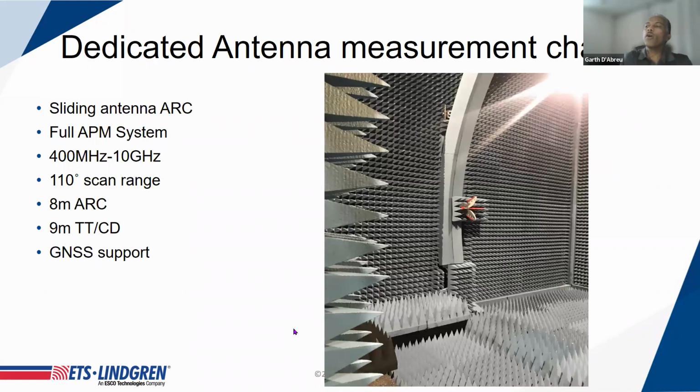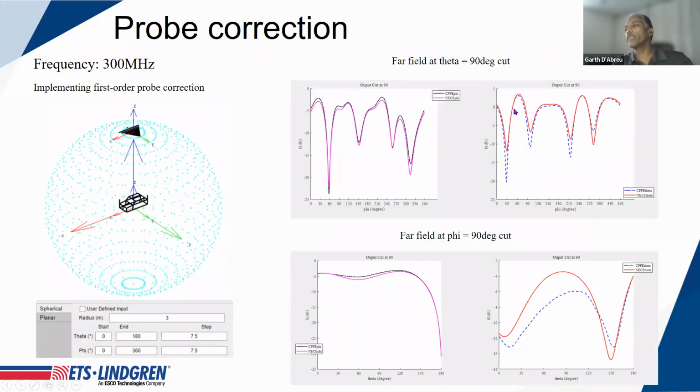This is one example of an upper hemispherical type scanning measurement setup, where the vehicle under test would be positioned and the antenna would scan over from the horizon over the top of the vehicle. This is a little model illustration of a vehicle under test sitting in a scanned bubble, as if it's floating in space. It allows you to make a completely spherical measurement of the vehicle. And from that, you can calculate all sorts of antenna-based and propagation-based properties of that particular antenna.